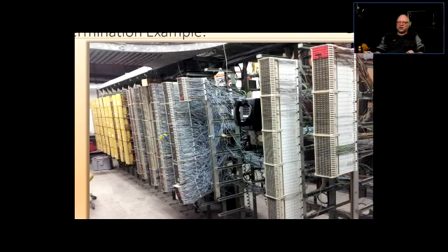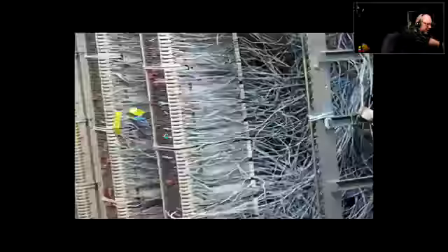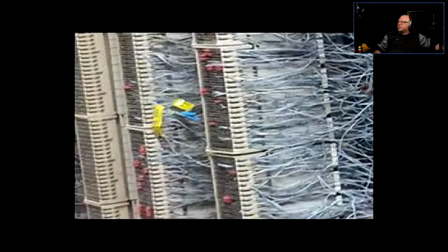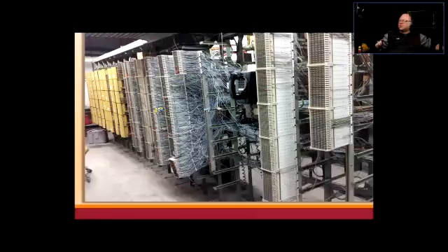So I had to use a toner, and I'll show you in further lectures what the toner looks like. I would stick the tone generator into the telephone outlet where the existing store was, and I would take 10 minutes to walk down to the basement and run my probe to see where the tone could be sounding. I would zero in on the area, make my way right to where the pair was, and make a couple of marks with electrical tape and write down what it is, because it was a renovation. I had to switch that store from one location to another, and then 2 months later I had to come back and switch it back.